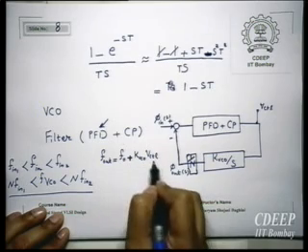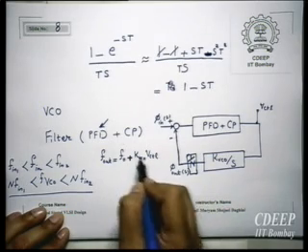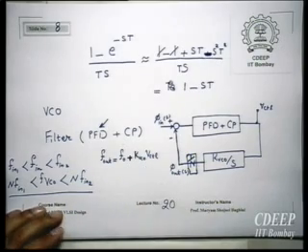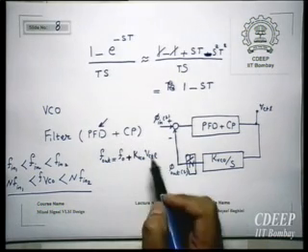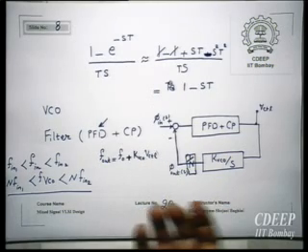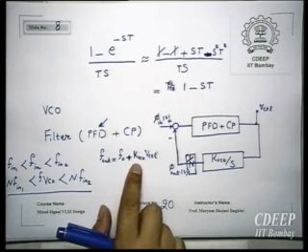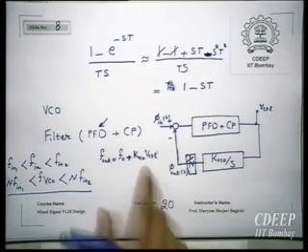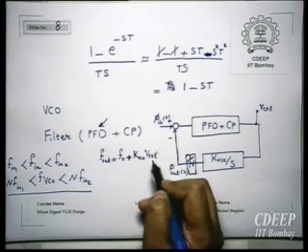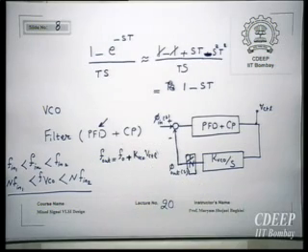I can even choose the range of VCTL according to the VCO I'm designing. Say, for example, the current starved inverter, which will be the component of a ring oscillator. So for that, I have a range of voltages, and accordingly, I get this VCO, and VCTL is the input.